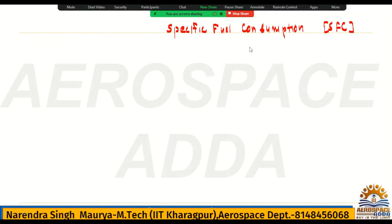If you are doing this calculation, then this is called specific fuel consumption. So, mass flow rate of the fuel per unit thrust. I mean, if you are burning 1 liter of fuel, then what amount of thrust are you getting after burning that fuel in the combustion chamber? That ratio will be called specific fuel consumption. Hope you understood. So specific fuel consumption is a very important parameter actually.